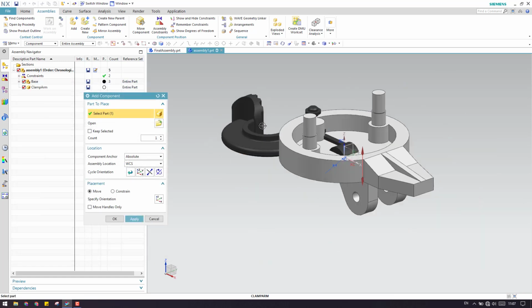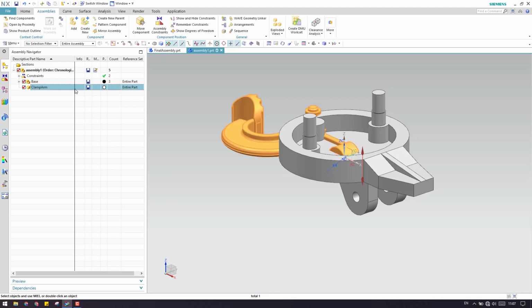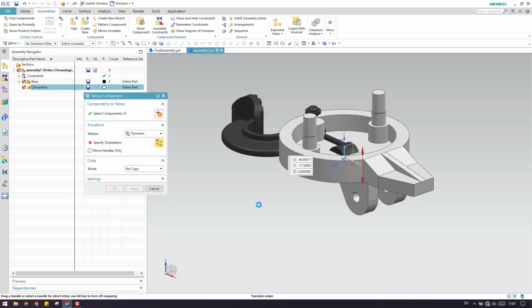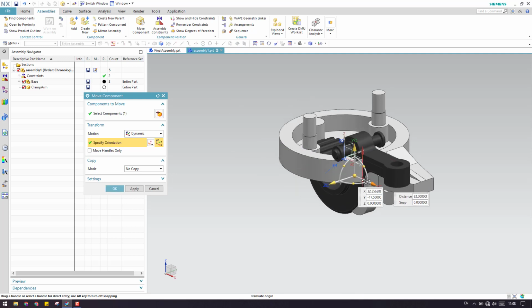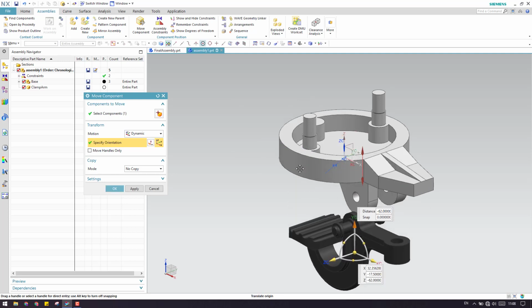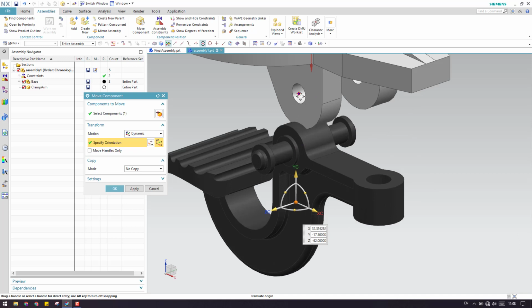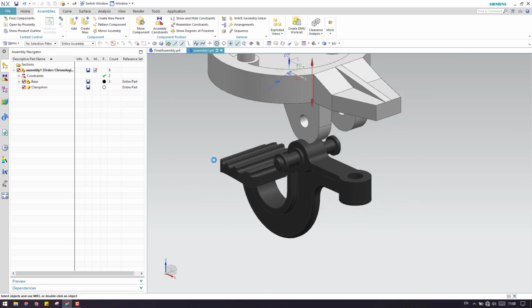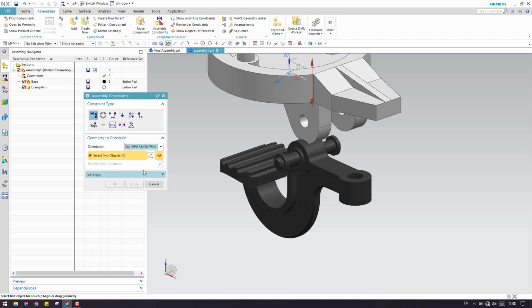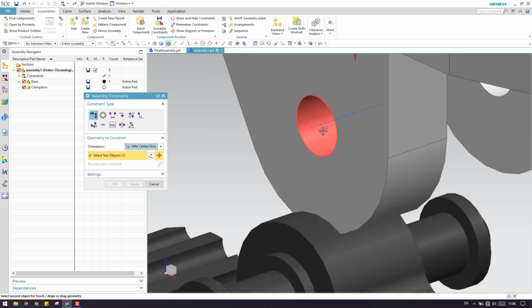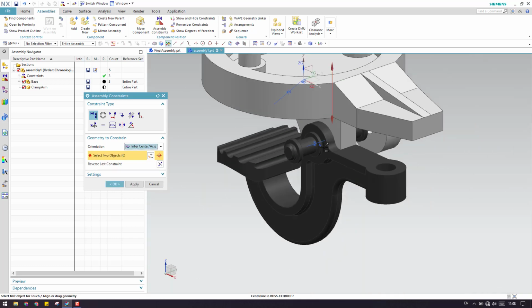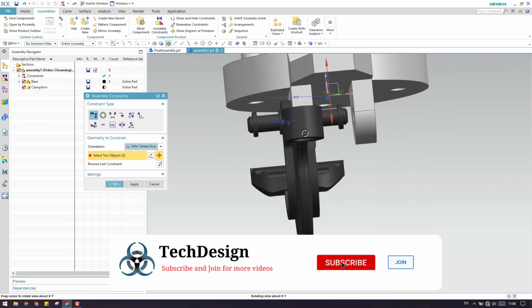So now this is not in a proper position, so let us... You can see this has to come and fit it here. So let us go to assembly constraint and make a central axis. So this center line should be at this. Okay, now it is perfectly coming.